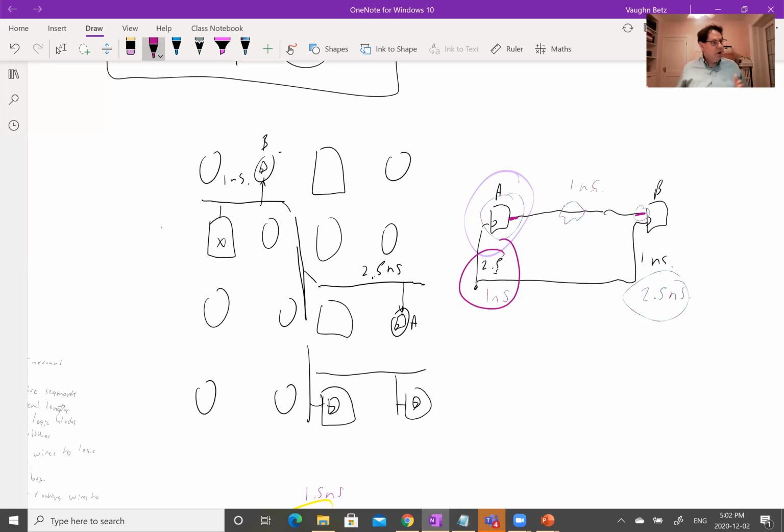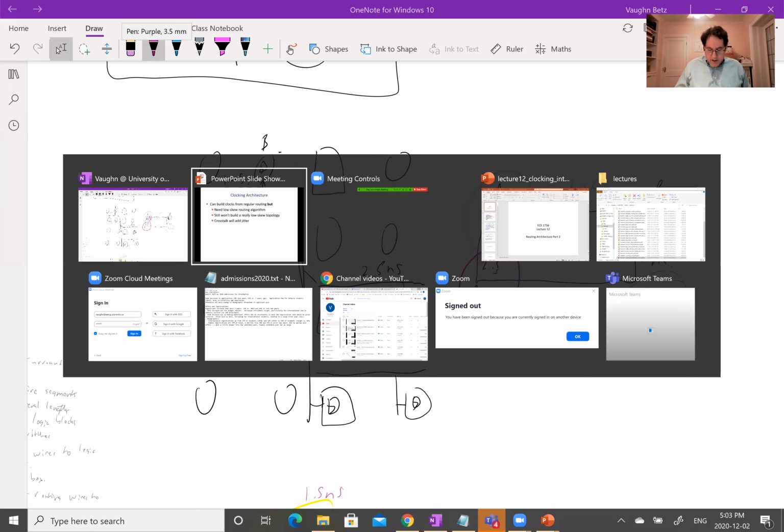It will hurt you in your clock period because, for example, here I'd have to assume the clock arrives late. It will also hurt me on hold because for hold I'll have to assume the clock arrives early. So jitter makes things ranges, and the timing analysis tool always takes the worst point in the range, which sometimes is the early one, sometimes is the late one. So jitter is really nasty. You want to keep it as low as you can.